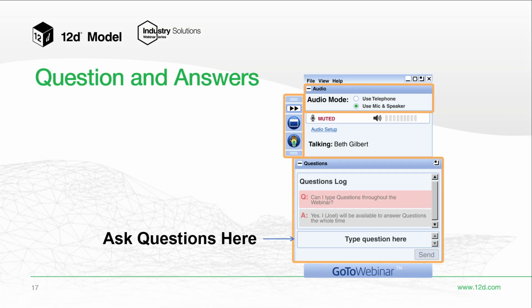Thanks, Dylan. I've got a couple here I'd like to read out live. We've got one from Daniel saying, is it possible to set up the Apply MTF defaults so all strings created are on the same model? Absolutely, they can be. You can just take out the wildcard so it doesn't take the reference string names, and they can definitely be in one nominated model if that's the way that you want to use it. I do find that having the model names with the reference string makes it a little bit easier for me to find, but you don't need to have the wildcard within the Apply MTF defaults, and you can just put those into strict nominated models.